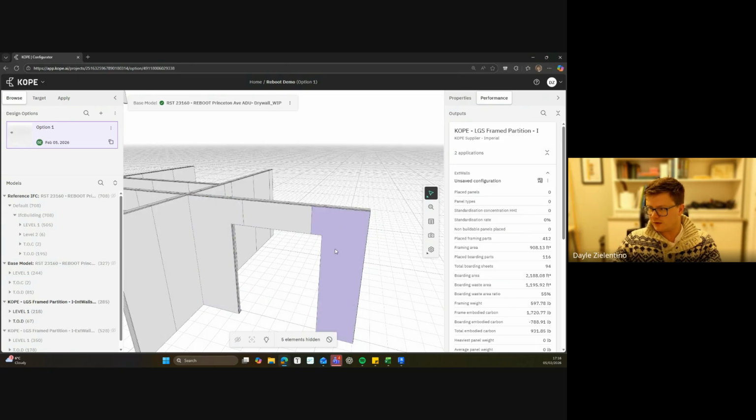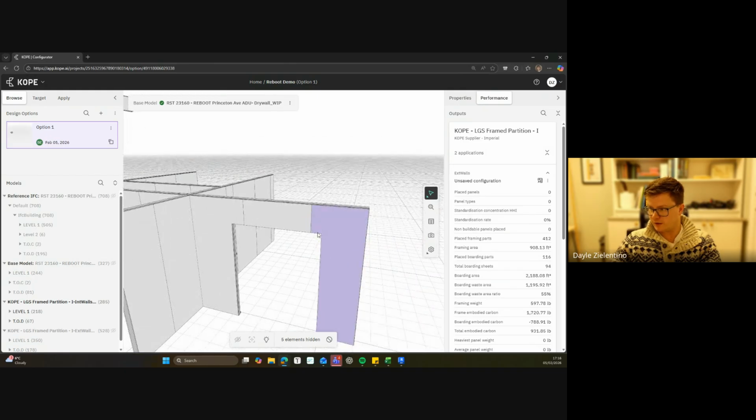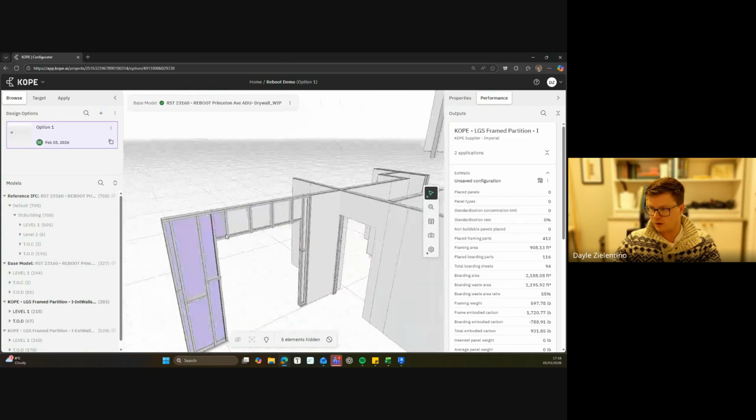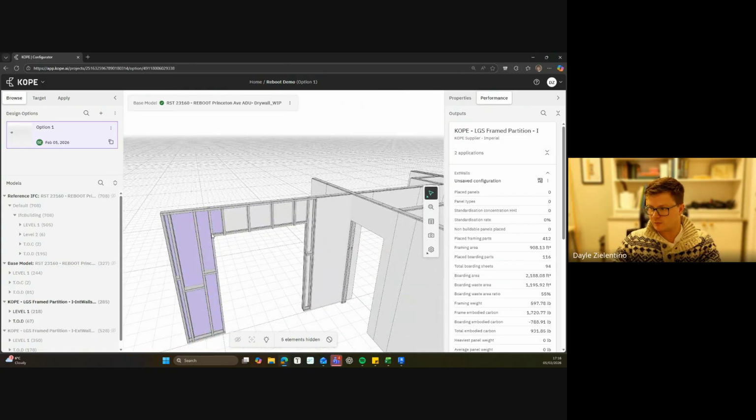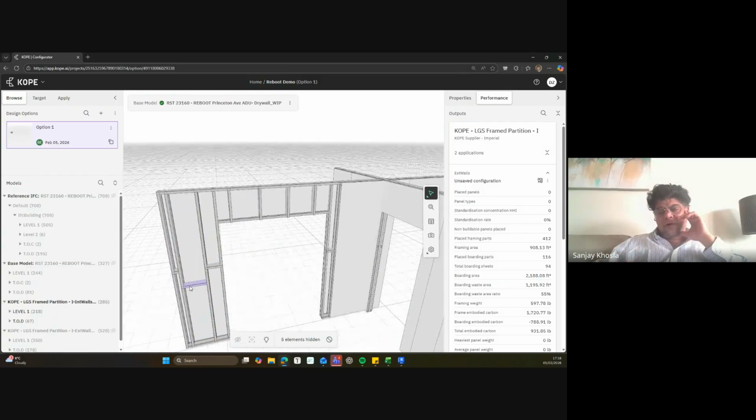So in order to place the board around the door opening, I have to allow the 6-inch gap to stop any cracking that happens with drywall. I have framed out the door jambs, I've framed out the headers to your rules, and then it's gone through and worked out where the stud spacings need to be to pick up board pickups and follow that. So this is powerful and very genius.